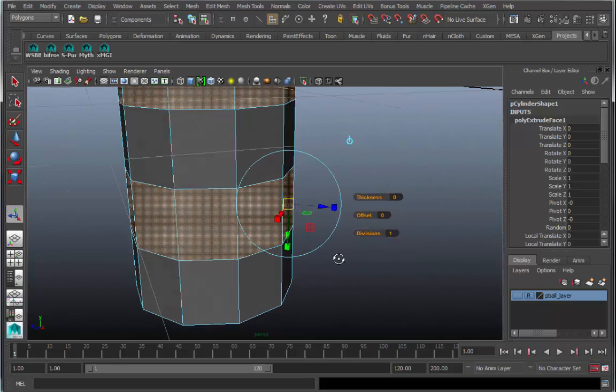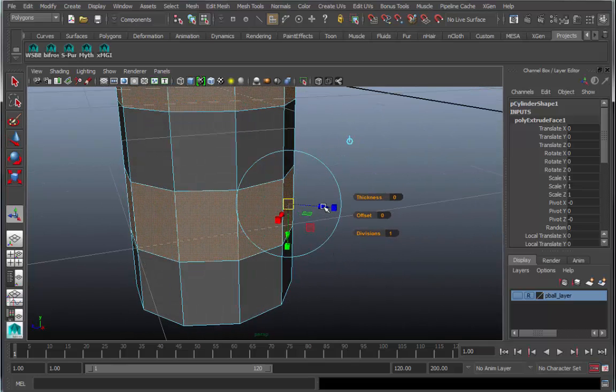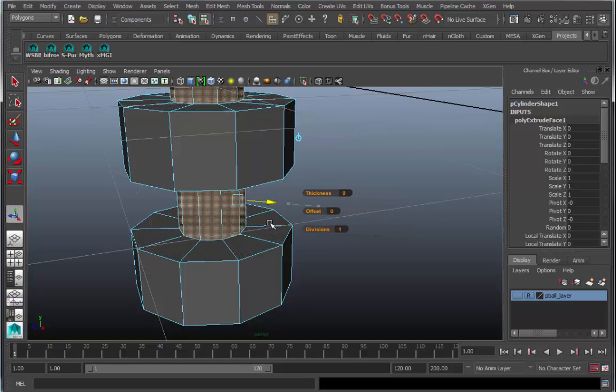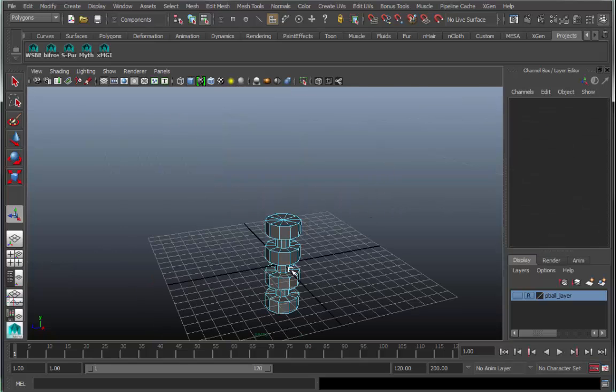And it's very important because you need to identify which way is out from that one control. Why? Because when we move it, it will move each and every one of these selected polygons in a relative fashion, not an absolute fashion, which is what we've been doing thus far. So if I grab the tip of this blue arrow and push it in, watch what happens. All of them get pushed in according to their normal. And so I've quickly made a nice little lightning rod.